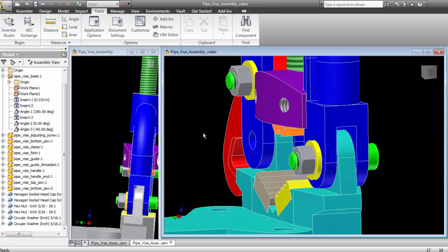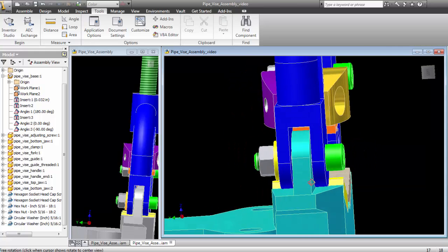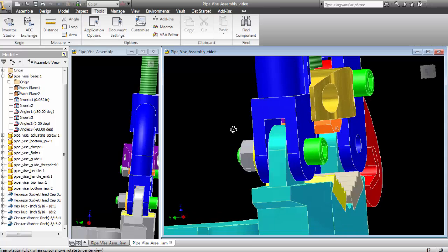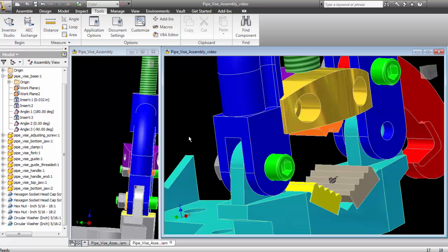Now, the one thing I failed to note, when you're talking about how long that thing is, it's the distance from where this head meets the fork out to the end of your threads. That's where the 1 1/4 inch comes from. So if you need to know, that's what's going on there.